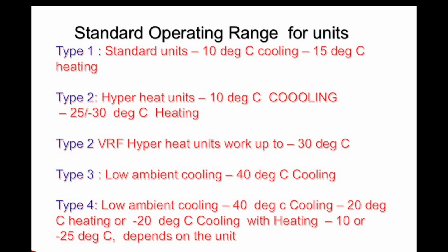You'll also need windscreens, along with specialized hardware and software. Keep in mind that a 208-volt 3-phase unit won't work down to minus 40 degrees Celsius, but with a low ambient hood and windscreens, these units can function at temperatures as low as minus 30 degrees Celsius.